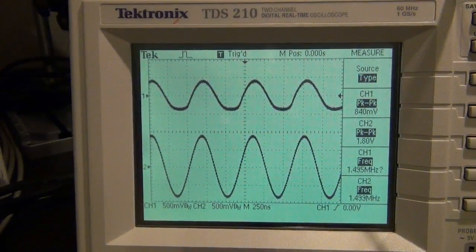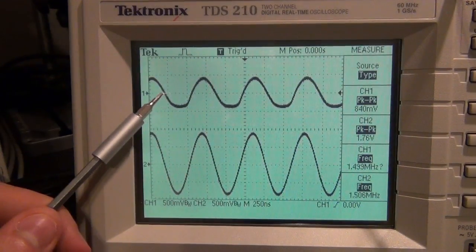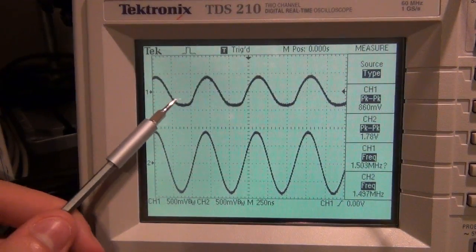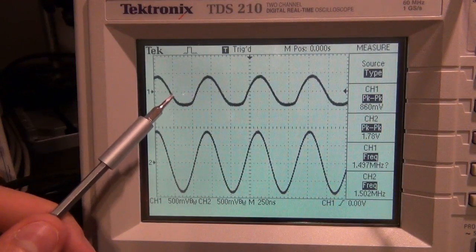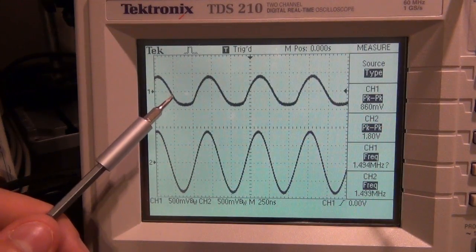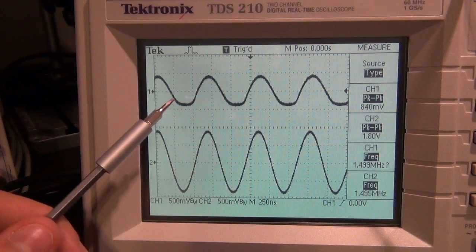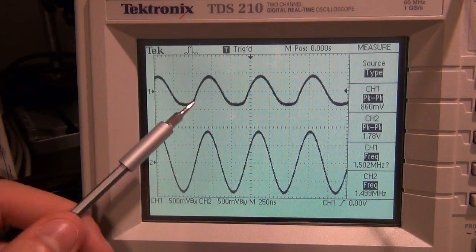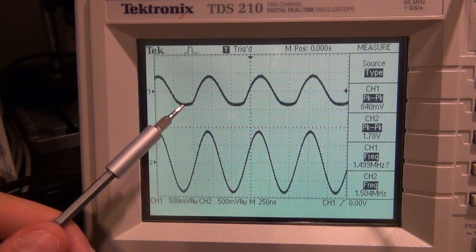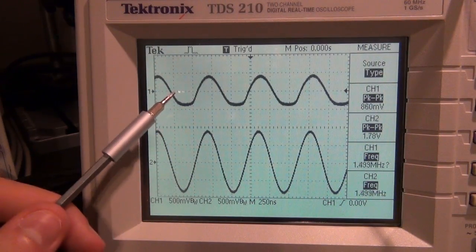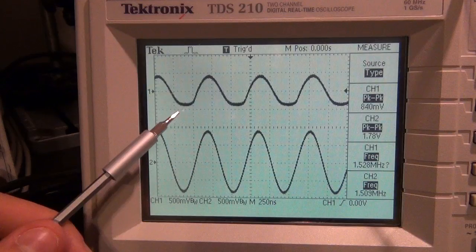If you can tell, the output doesn't look sinusoidal anymore. It's clipping at the bottom. And that makes sense, because the way I've connected the diode, when the signal goes below 0 sufficiently, the diode's exponential current kicks in and clamps the output. So sometimes people use these diodes to clamp an output, to make sure it doesn't get larger than a certain value.